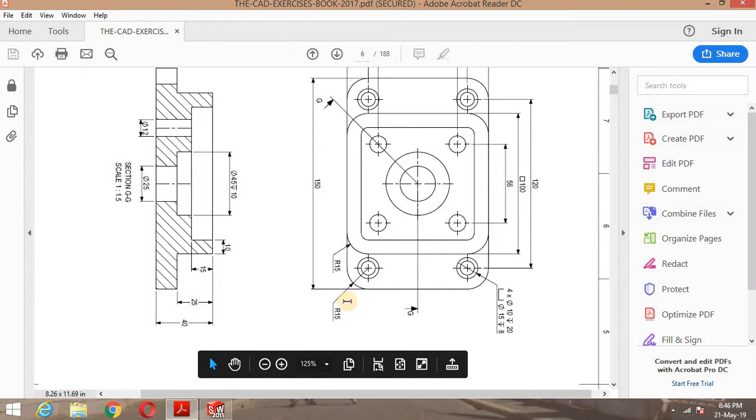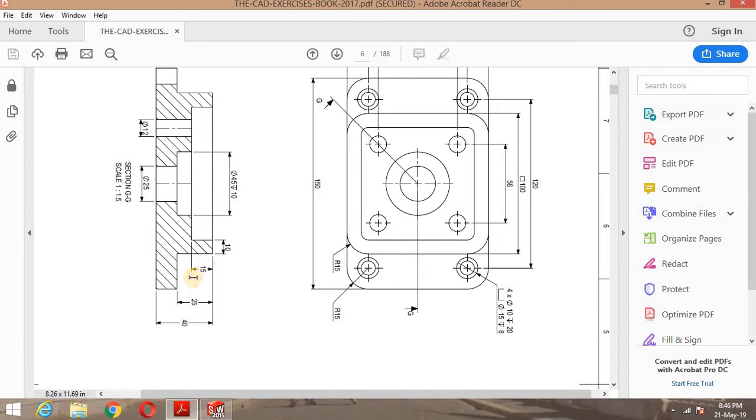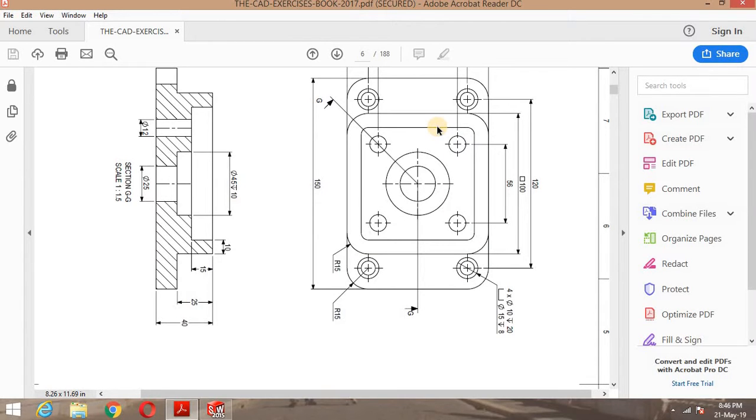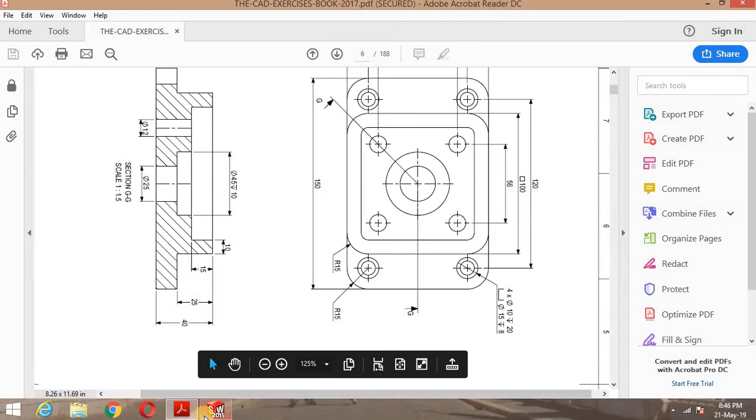Now the main interesting point comes here. We are at this datum level, so our drawing is at this datum level. Now again I have to make a rectangle at a distance of 15, and I have to extrude it till 15. So I need to make a rectangular sheet which has a width of 10, and the extrusion should be of 15. So let's make it.